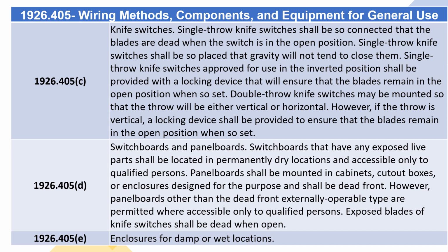Double-throw knife switches may be mounted so that the throw will be either vertical or horizontal. However, if the throw is vertical, a locking device shall be provided to ensure that the blades remain in the open position when so set.